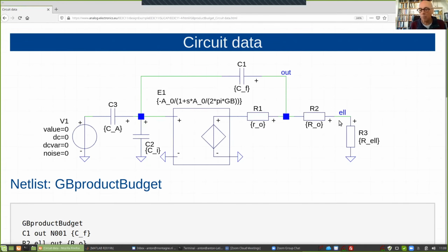stays at about 100 ohm and this capacitor, which is 3 pF, and 100 ohm, which is 300 picoseconds, which is 500 megahertz. So whatever this RO will be, it will never cause a pole in a dominant group. It will always be a non-dominant pole on this ground. So that is important to realize. So I use this model, but basically we are only going to work with RO equals 0, because whatever I put in it, it will never have a dominant pole.